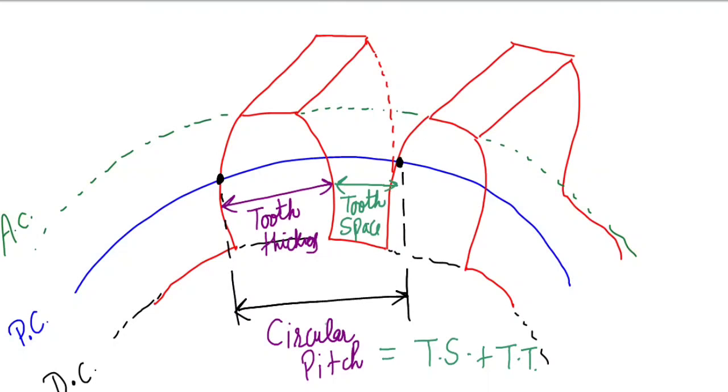So can you say that, Anjali, if two gears are meeting, the tooth space of one gear is exactly equal to the tooth thickness of the other gear, then and only then the other gear can enter between the tooth space of the first gear, na? Otherwise it cannot enter. Suppose you are entering a house and the door is so narrow that you cannot enter. So how do you enter? This means whenever two gears are meeting, or you can say meshing or engaging with each other, the corresponding tooth space must be equal to the tooth thickness of the other gear. Otherwise the motion cannot be transmitted. Okay, this thing you need to understand.